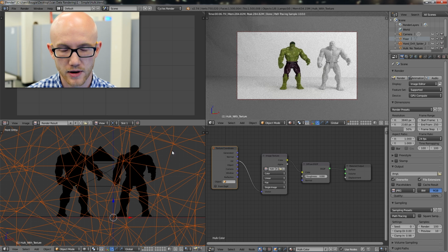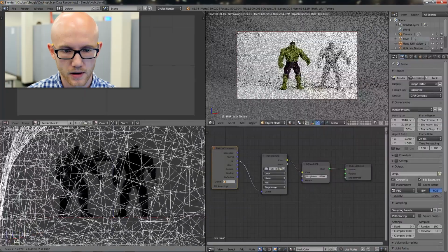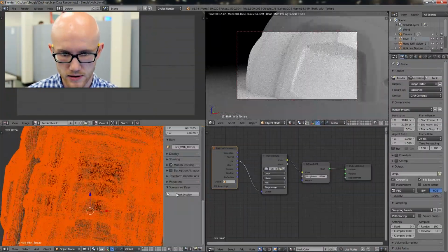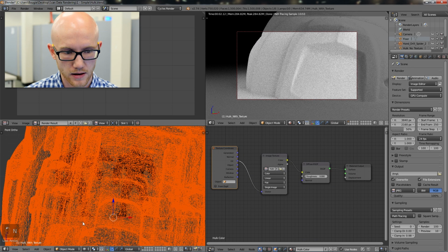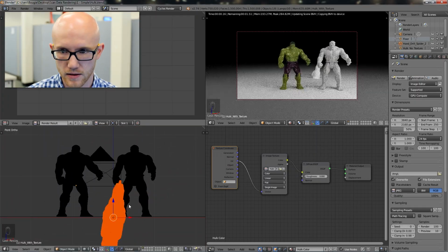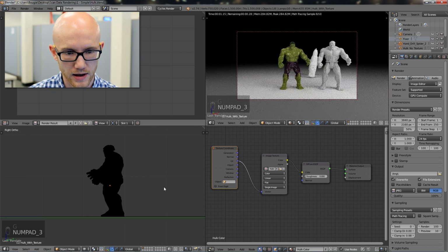It comes in, pretty much everything you import in the Blender comes in very, very large. Blender doesn't use real-world units, so we are going to press the S key and scale this down. And actually, I forgot to turn on screencast here. Okay, so now you'll be able to see here in the bottom left-hand corner what buttons I am pressing. So I'm pressing S again and scaling this down. G to grab it.